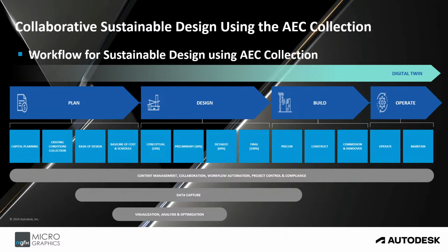Then environmental analysis. Revisit Autodesk Forma. Take the refined Revit model, export it, and send it back to Autodesk Forma for further environmental analyses, including wind simulations, daylight assessments, noise analysis, aerometric analysis, solar impact studies, all the different types of analyses that are available. The key features are comprehensive environmental analysis tools, and the outcome: a validated design aligned with all your sustainability goals.